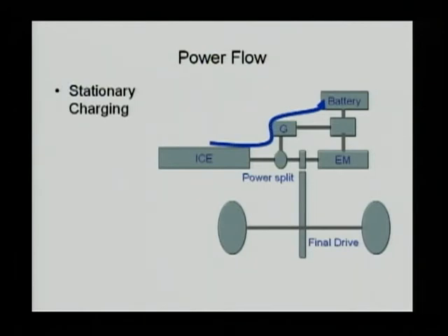One thing you should be aware of is that in many hybrid vehicle systems, there's no alternator. There's no small generator that can charge the 12 volt battery or the 14 volt battery in the vehicle system. However, you still need that 14 volt battery for many auxiliary equipment uses, such as your wipers, door locks, powered seat, headlights, tail lights, okay? All of them are going to need power. That power is coming from the 14 volt battery. And that 14 volt battery needs to be charged.